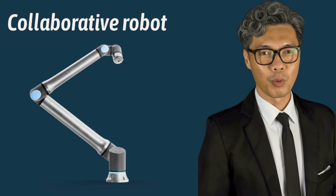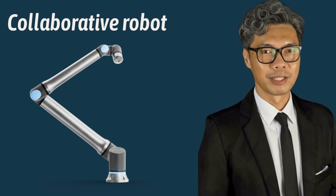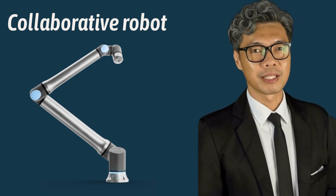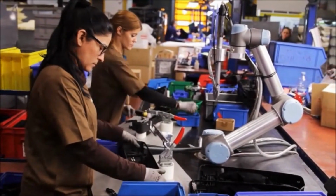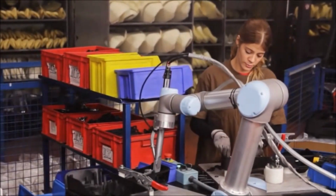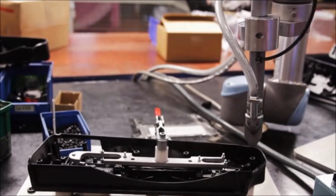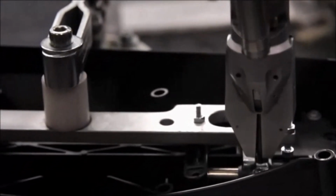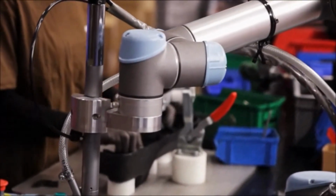The fifth type is the Cobot, short for collaborative robot. Cobots are designed to work alongside human operators without the safety fencing that traditional industrial robots require. Setup and redeployment are faster compared to industrial robots, which makes cobots attractive when you need flexibility across different processes or product lines. Cobots also generally have a more familiar user interface. The operating experience is closer to what you know from Windows, Android, or iOS compared to the traditional programming interfaces on conventional industrial robots. This makes cobots easier for operators to learn and use on the floor.